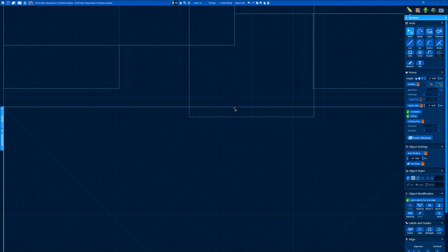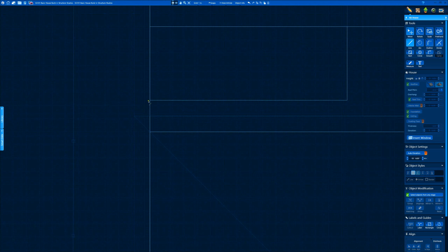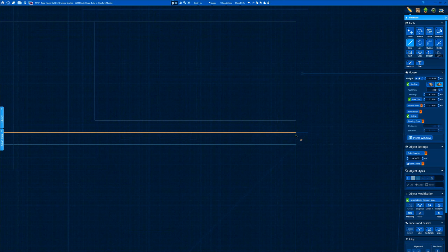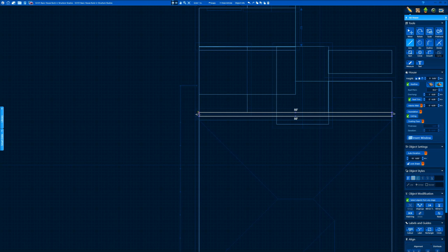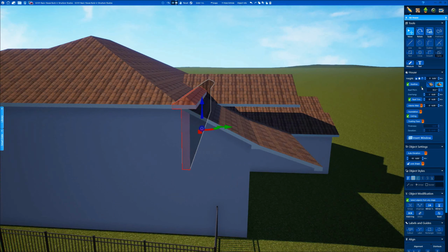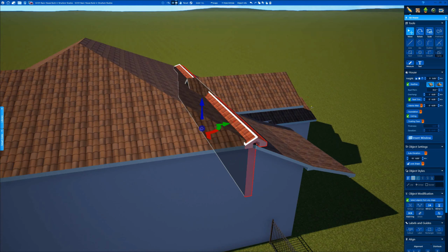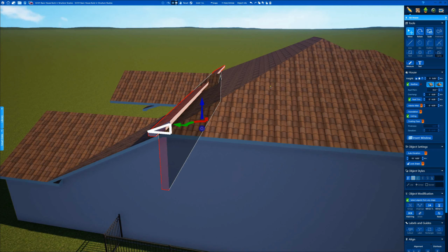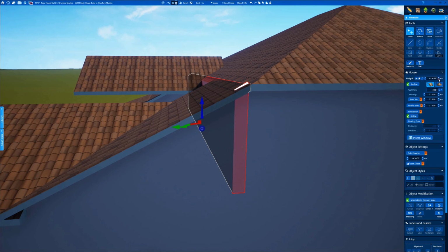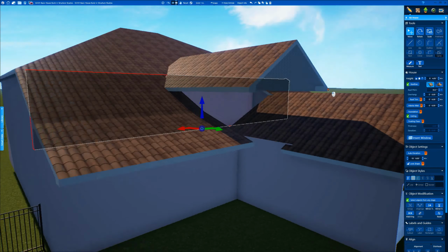And this is why you separate your roof lines from your walls, so that you can manipulate the walls and close those gaps. So here's a little filler piece. You're going to use this a lot. If it's an 18-inch overhang, it would be 18 inches. If it's 24 inches, it would be 24 inches. So it'll be whatever it is. This one is 12. So we're going to make sure all of our gables are turned on. Make sure our pitch is correct. We're going to turn off roof line. We're going to turn off roof trim, and we're just going to drop this down in place and watch that gap just disappear. See there, that piece?